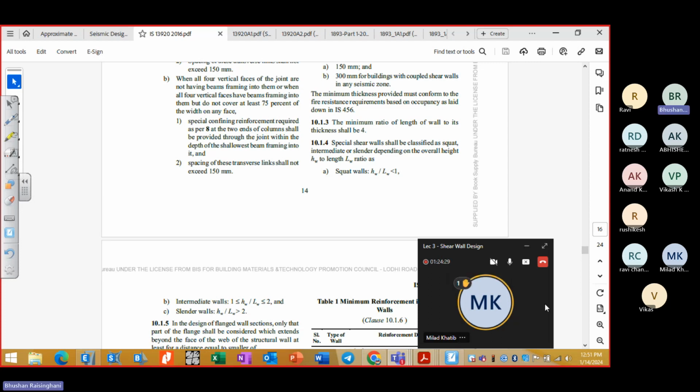Yeah, okay. So it is also a shear beam, as he said. It is a coupling beam, mostly a beam governed by shear and not by flexure. So its size has to be that way. You cannot assign a 300 size beam and call it a coupling beam, because it will not resist or transfer those forces.